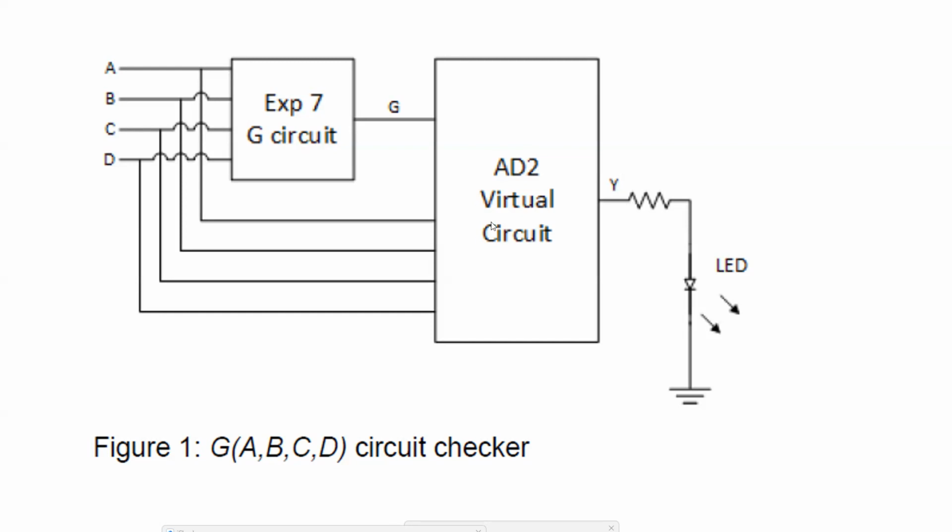So again, the way this one has to work is, when you try all possible values here, if your circuit is correct, correct means for every input value, the LED is off. If it happens that for one input the output here was wrong, then in this case, this one can turn on. For sure, if your circuit is correct, that means this LED is going to be off all the time.